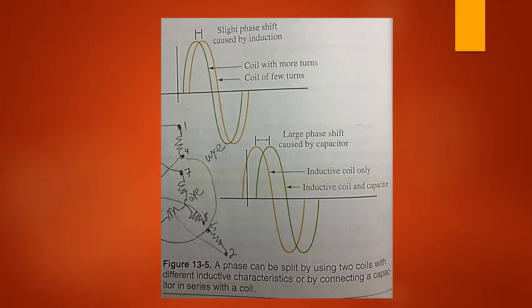In industry, three-phase electricity is used to run large induction motors. Other means must be provided for starting single-phase induction motors. If, for instance, a single-phase current could be divided into a polyphase current, the starting problem would be solved. This action is possible, and it is called splitting phases.